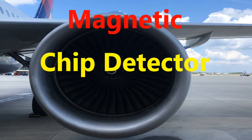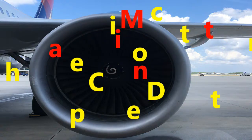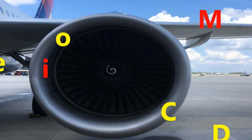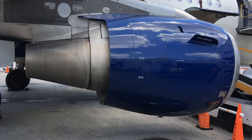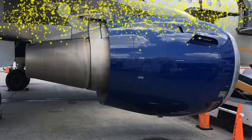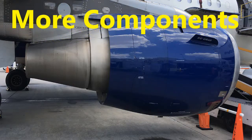Okay, and then as far as examining the chip detector, you need to be careful and pay attention to what's there. Also we want to ID it properly. I mentioned that before about serial numbers and making sure that you have identification of the actual chip detector. Okay.